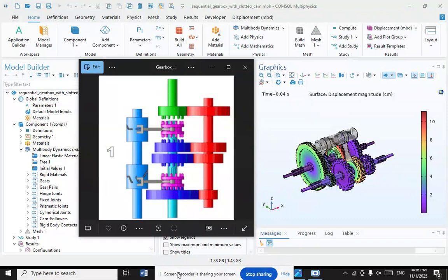And what about the design? A sequential manual transmission is unsynchronized and allows the driver to select either the next gear, for example, shifting from the first gear to second gear, or the previous gear, for example, shifting from the third gear to second gear. It is operated either via electronic paddle shifters mounted behind the steering wheel or with a sequential shifter.